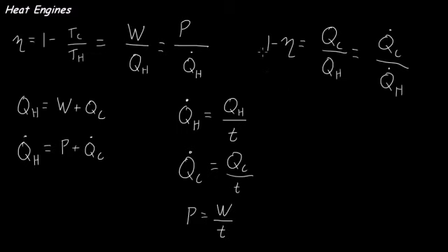And I've got the waste percentage, which is 1 minus the efficiency, is equal to my waste heat divided by the heat input, or my power waste divided by my power input. So if you understand all of these equations, you basically understand most of what you need to know about heat engines.